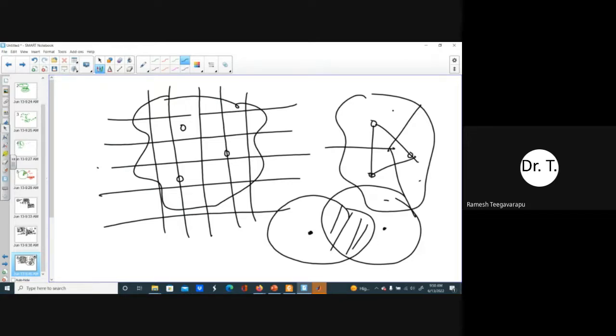So because rain gauges are very sparse, we don't have a lot of rain gauges, and they try to mute the variability because of the averages we calculate and so on. Even if you do kriging or even if you do very good geostatistical methods, the problem is that we mute the signal, we reduce the variance. So in that process, your distributed hydrologic models may not work very well.